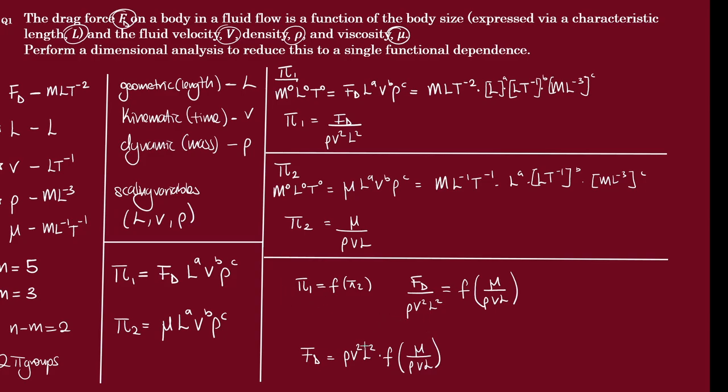So this is all we've been looking for in the minutes of explaining Buckingham's pi from the conceptual introduction. So remember the steps we took. We listed our variables, listed the dimensions beside each of them, counted the number, counted the independent dimensions, and performed the subtraction to know the number of pi groups you have. So if you look, we had 2 pi groups. This was 1 and this is 2.